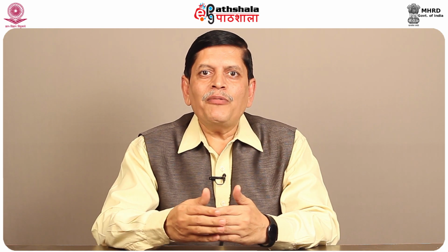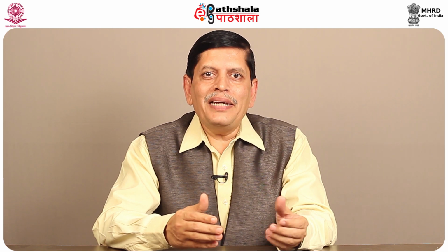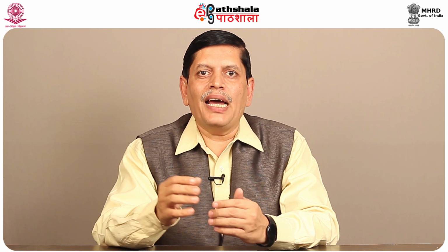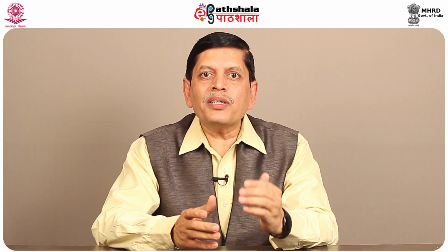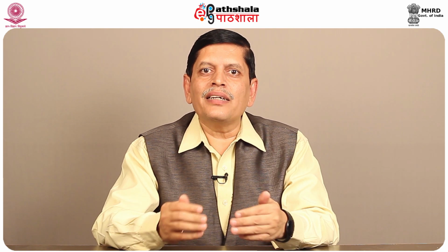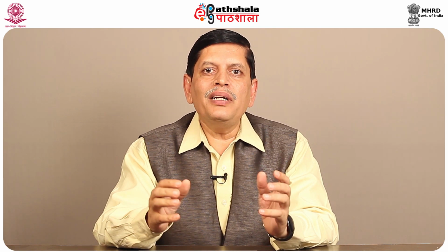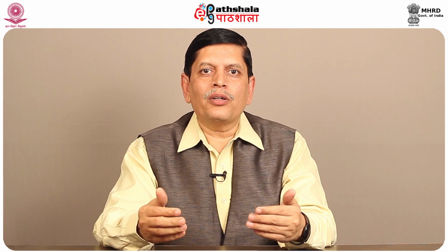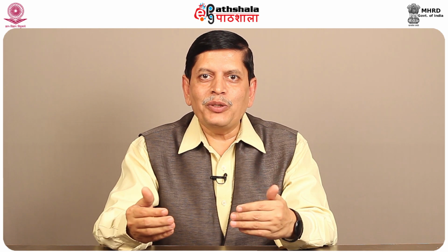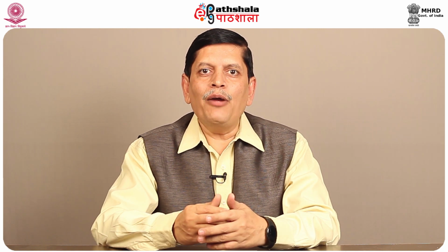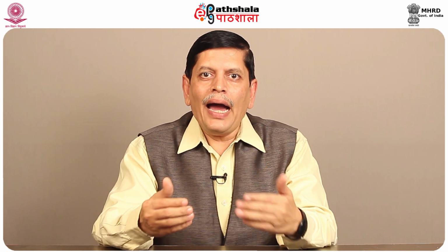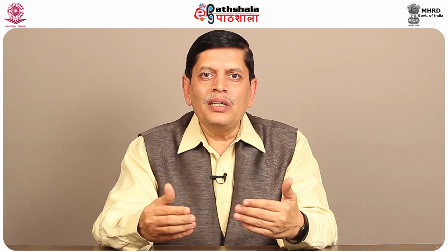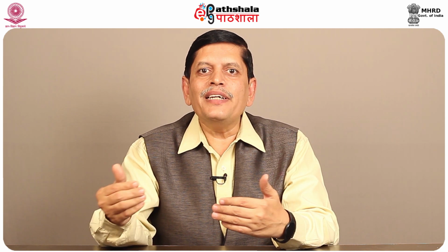In the previous session, we have discussed how 1-bit ALU can be designed, and the same concept can be extended further for n-bit ALU design. But there is one important thing that we have to understand, that here we have assumed all these building blocks are ideal building blocks. But in real life design situations, we know that every logic gate or building block has inherent delay, and this delay is because of the propagation delay.